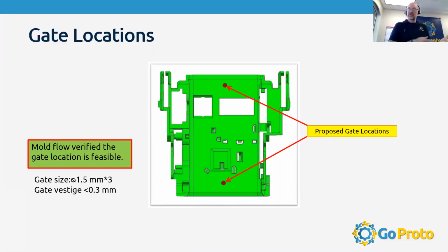I guess the short answer is that it depends on the application of your part and the material we're using. We have what are called hot runner gates, which is what these ones are, where the material is heated through a manifold all the way down to where it touches the part, as Matt mentioned, or we have cold runners, which will leave some material on the part. The parts are a little bit more expensive with hot runners, but the mold is less expensive. So there's a lot of different variables, and we have all of the options available to us, and so we can talk through the project and the part with you and make a decision on what type of gate to use. I hope that's helpful.